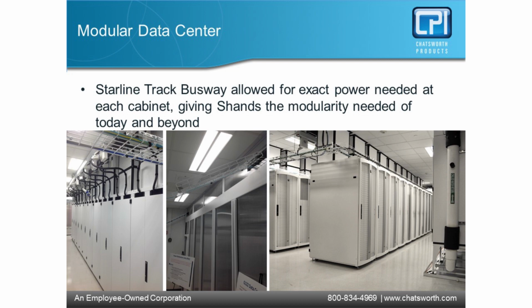Now, whenever I was over in Europe, I couldn't understand why there was so much desire for cold aisle containment. A lot of it came down to their elevation. They had a very tight slab-to-slab elevation, and it was very hard to incorporate hot aisle containment and create that return plenum.